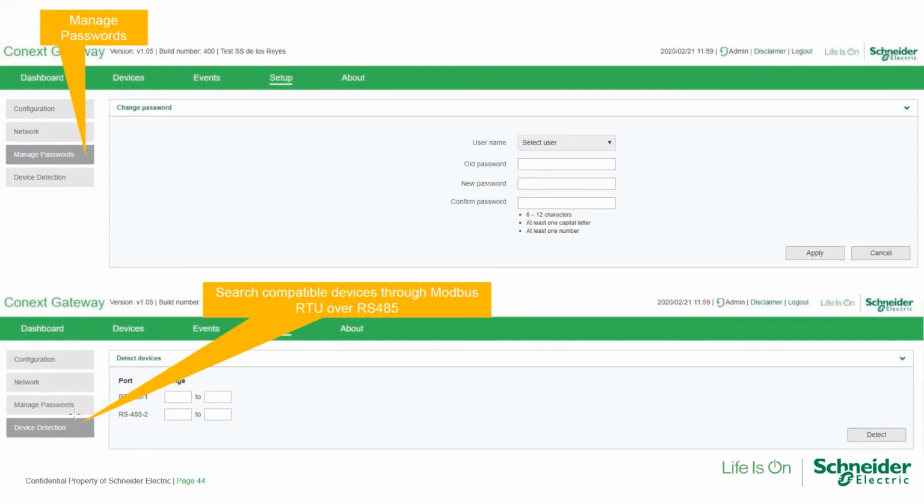So this is a manual process that needs to be done at least once when you connect your RS-485 devices. It's still Modbus, but it's not Modbus TCP, it's Modbus RTU, the communication happening through RS-485. The BMSs on your batteries, by the way, will be RS-485 devices as well, which have to be detected, right?